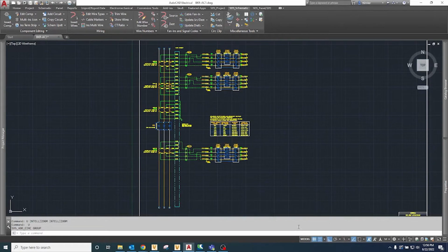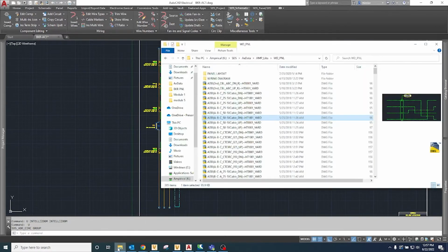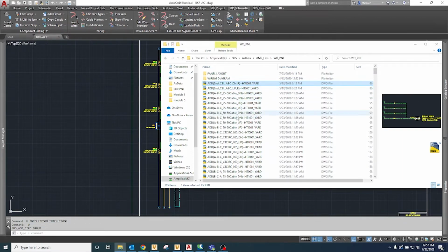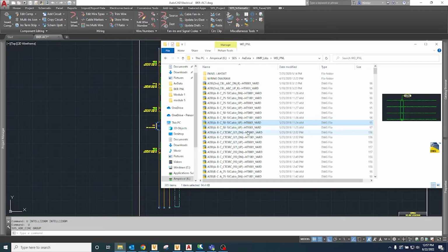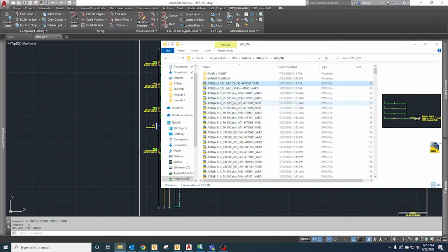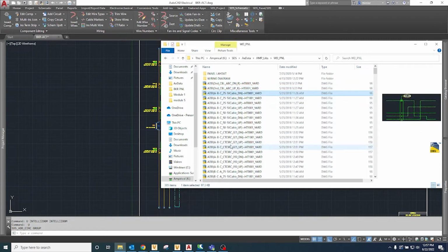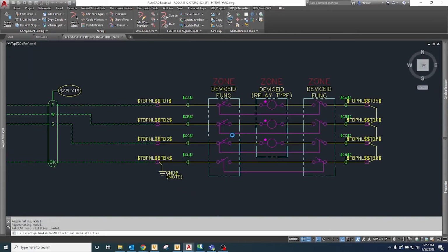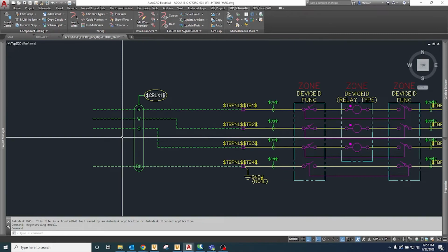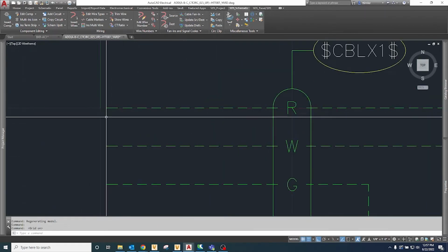SDS Add Circuit looks into the panel symbol library folder for the circuit files. This is probably due to the fact that it was originally programmed for wiring diagram symbols. To break down the file names based on the example circuits I previously inserted, the prefix add is for the SDS Add Circuit command to find the circuits. In the parentheses is a user-defined description. In this case, we use BCA to represent a phasing configuration. 50/50 indicates a 1/2 inch spacing on each end. Cable indicates that it's only the cable that's going to be inserted, and up or down indicate the final cable bubble position. The tilde symbol that follows separates that user description from the target symbol file's name. For more information on the file naming convention, see the SDS help file under the Add Circuit command.